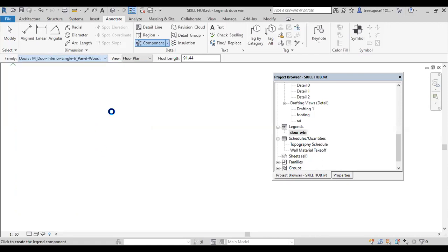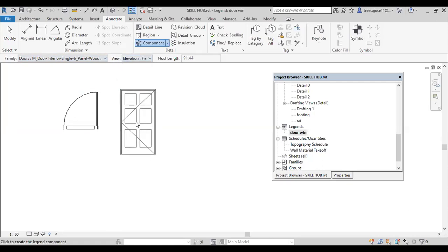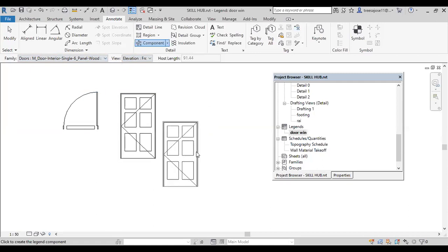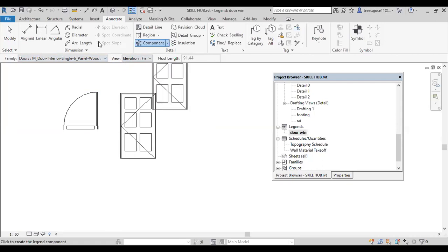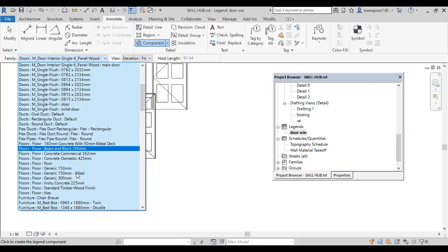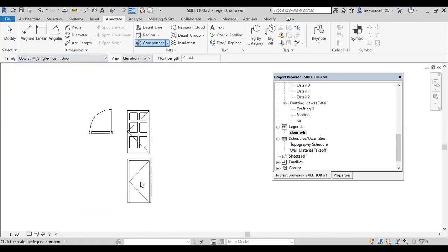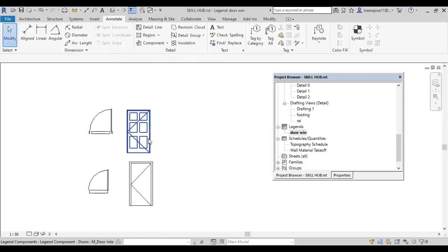If you select that, actually this one is the plan view of my door. Then after that, I have to create the elevation. You change this view to front view. Automatically, you can align this also easily. Okay. Then below that you need to add the door. That time you come under, select the door. Then place the plan view here. Later on you can add the dimensions and numbers or something with the help of detail view.